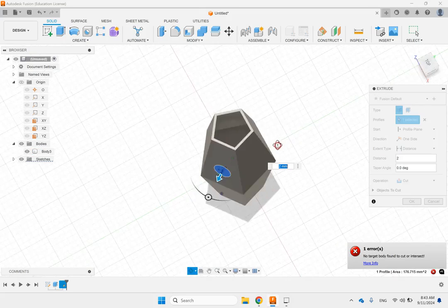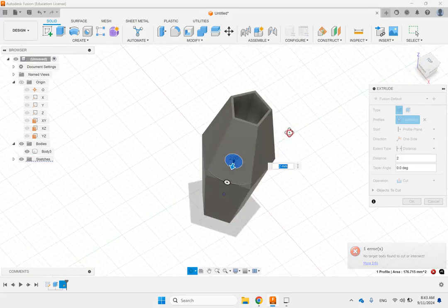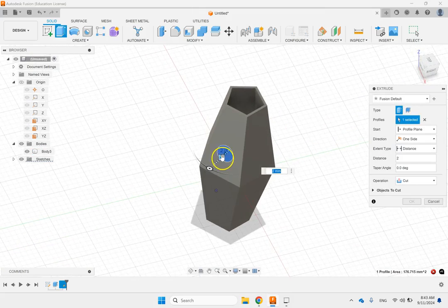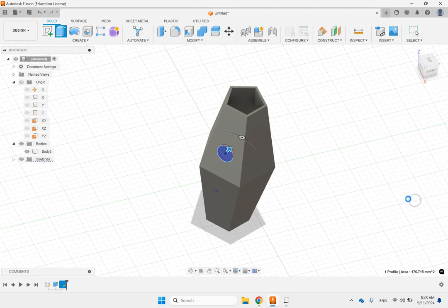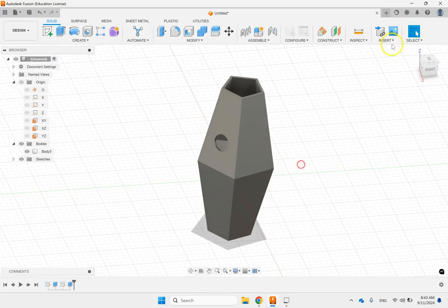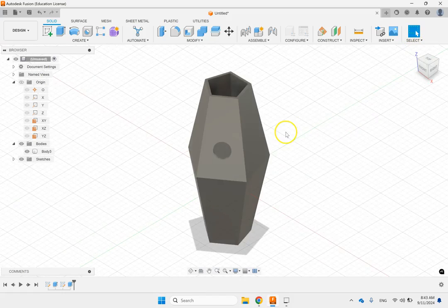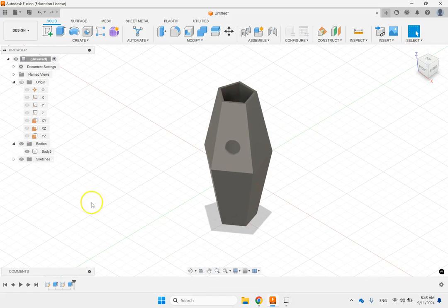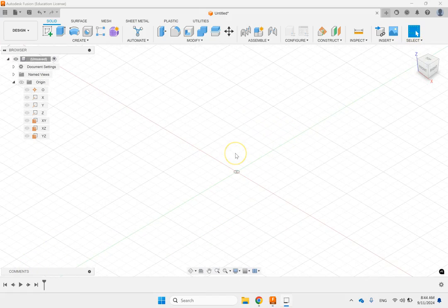And you see right now it is going out, which is the wrong direction. You have to Cut-Extrude in. So you have to go backward in, something like that. So you have to do -2 basically, or -3 or something like that to go inside. And if you do that, then there we go. You see the cut is made. So Cut-Extrude is within the extrude basically by just changing the type of operation. Now, one type of creating 3D objects is with extrude and Cut-Extrude.